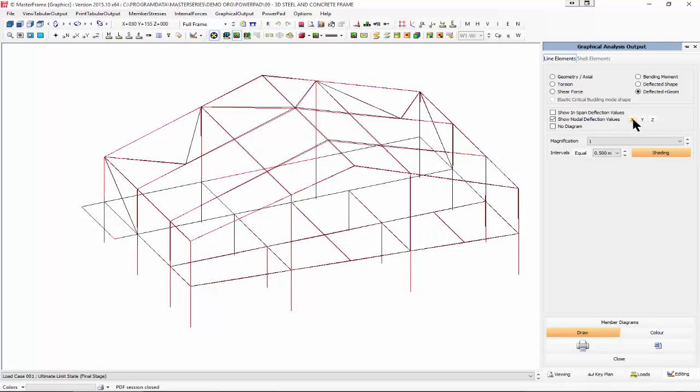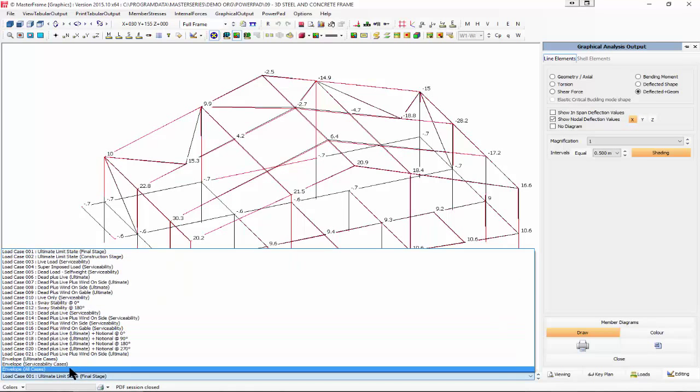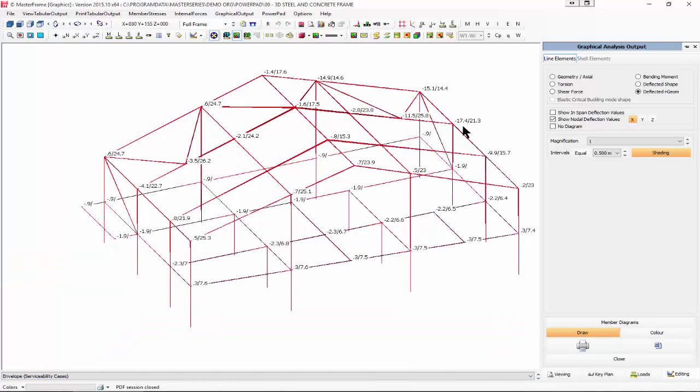More reassuring. So let's look at our X displacement, so we can see that under ultimate. But let's just go for surface cases. We can see that we're moving 21 mil horizontally on these in the X, and we just check out the Z as well, and we're moving 35 mil, 45 mil up here at the apex in the Z axis. Very simple, it's moving that way, backward and forward. So because of the way the bracing and everything's working, we'd probably need stiffer bracing to make this truss not move so much out of plane. Very interesting.